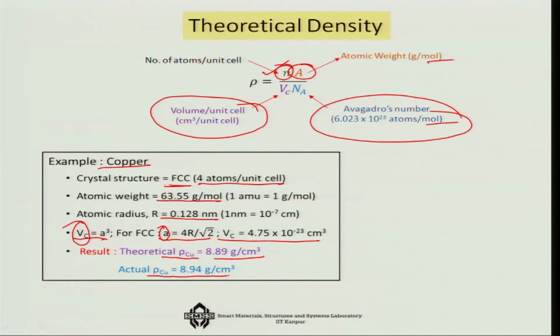So, that is how we can see what has contributed to the density of the atom. The crystal structure has contributed to the density, other than all other things like atomic weight, atomic radius, etc. Thus, if you know the crystal structure, you can actually predict the kind of density that you can expect from a particular structure.